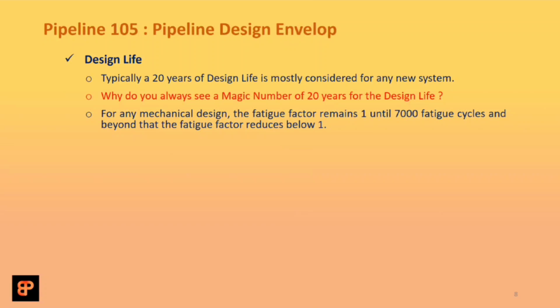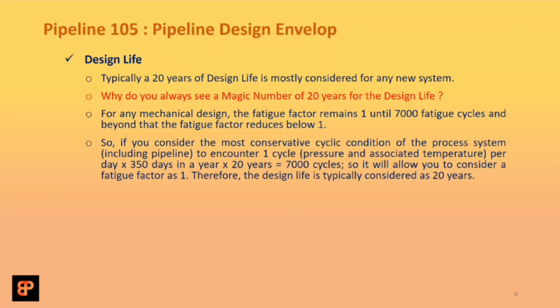So up to 7,000 cycles, the fatigue factor is 1. That means fatigue has not much or no impact on the thickness selection, which means the economics of the system. So these 7,000 fatigue cycles are converted into design life. How? Let us see that.